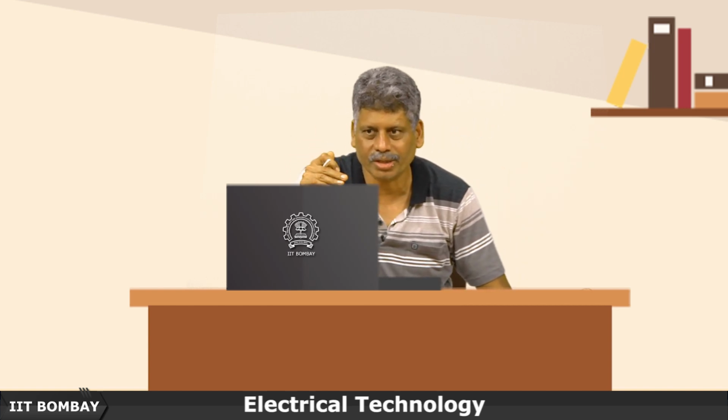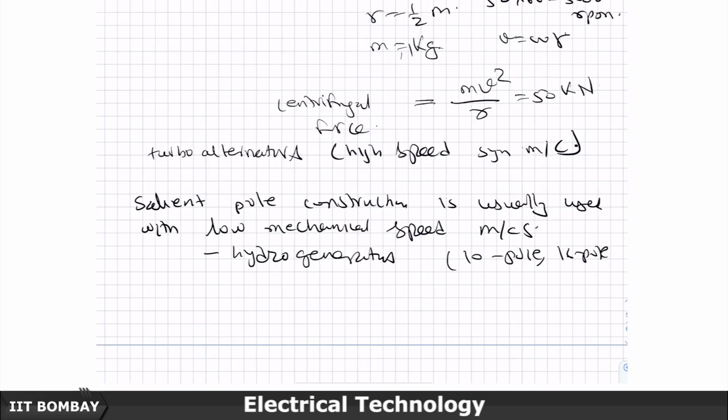And if the speed of a device is constant, then it means that you can also get a constant torque system. So, the ripples, the oscillations, etc., those problems sort of go away. And this is possible with a nice symmetrical 120 degree separation in a three phase system. If you had a two phase system also, you could have done it, but then the two should be at 90 degree with each other.